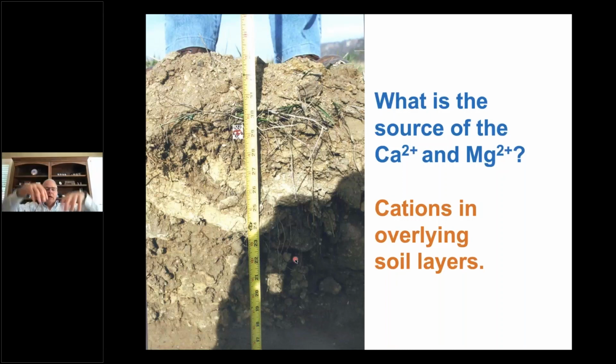So those calcium and magnesium above were making their way down with infiltrating water through the system and interacting with the GCL. And you think of a GCL, it looks at, would I rather have a calcium or a sodium? In a simplistic way, it says for a calcium, I can get 2 charges relative to 1 for a sodium. It's like getting $2 for $1.